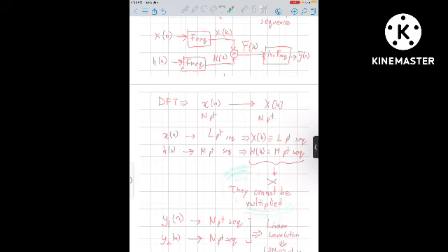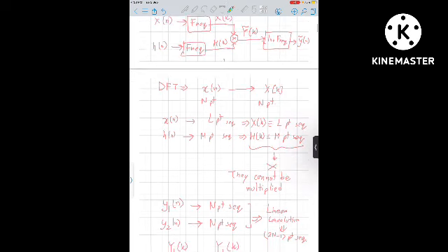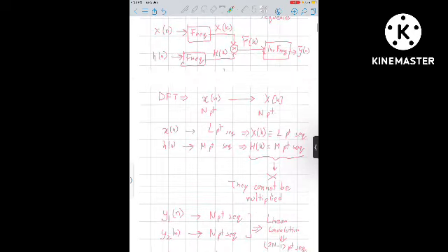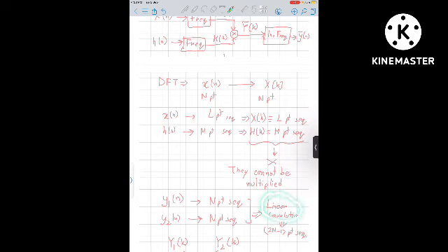So often what is done is this. Let us now go into circular convolution. Whenever we have a signal y1[n] which is an N-point sequence, and another sequence y2[n] that is also an N-point sequence, their normal convolution, or linear convolution, gives us a 2N minus 1 point sequence.